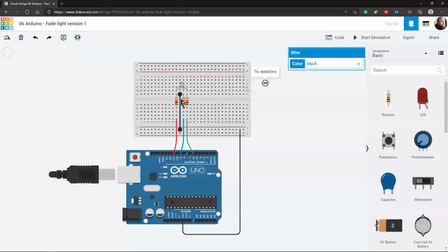Now, there is another type of RGB LED, just to make things more confusing, with a similar setup where you have to look for the pins where they'll have one for red, green, blue, but in a different order. But this common pin is then instead the anode, being the positive. In that case, it just means you have to tweak your code a little bit and change the circuit some. So in the simulator here, this is an RGB LED that is a common cathode.